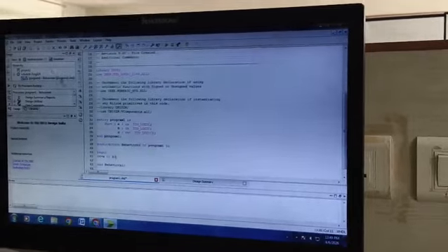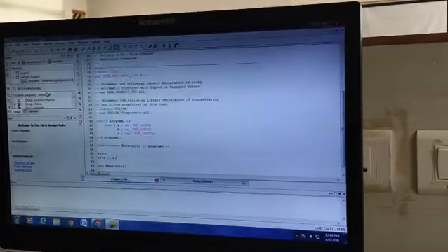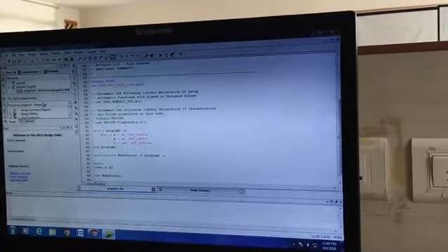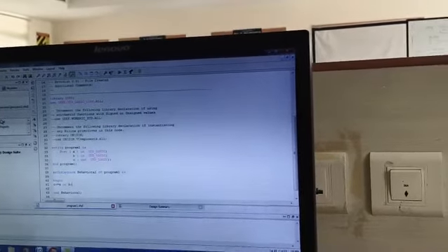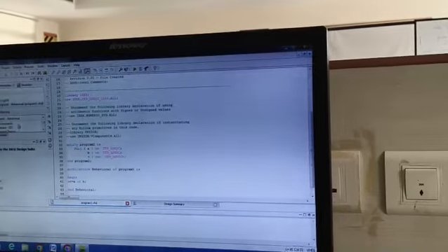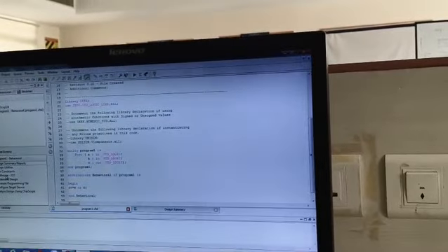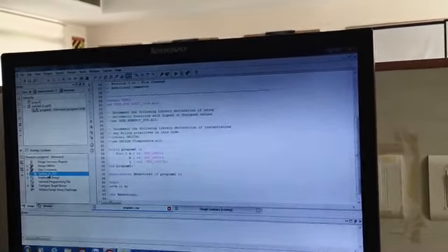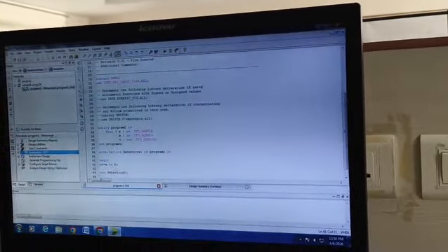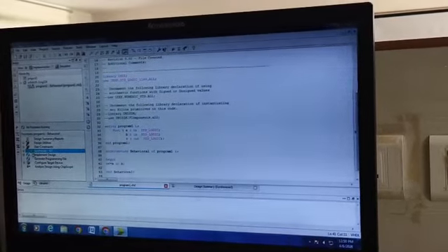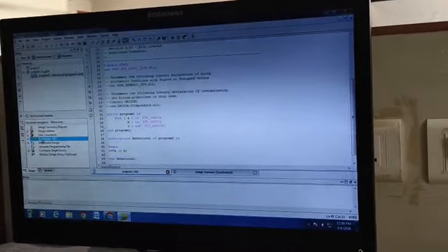Once the program is typed, save it. Before running, we have to check it, similar to a C program, where you compile before you run. In this tool, we have to synthesize the program. On the left side we have Synthesize. Double click the Synthesize tool and it keeps synthesizing. The system checks the structure of the entire program, and when we get the green tick, it is okay and ready to run.